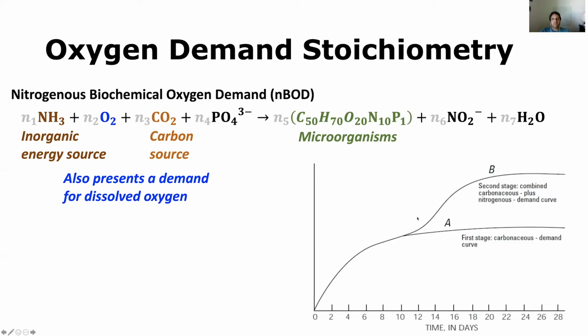All right, but if we had some kind of industrial wastewater, or if we're conducting a test that lasts a longer period of time, we would have to consider the fact that the oxygen depletion might represent not only the carbonaceous demand of carbonaceous energy sources, but also the nitrogenous demand of oxygen due to these inorganic forms of nitrogen.